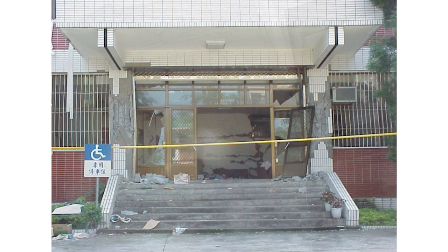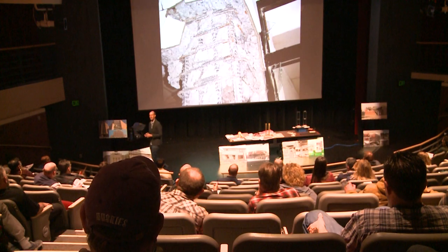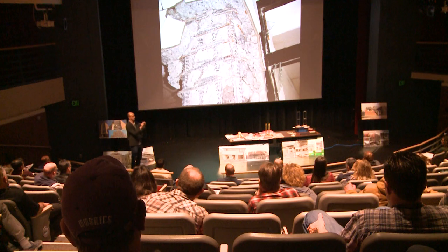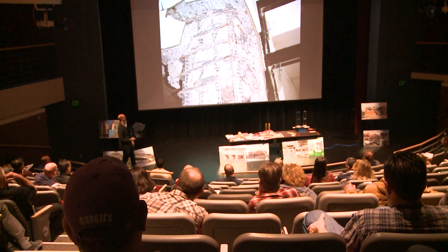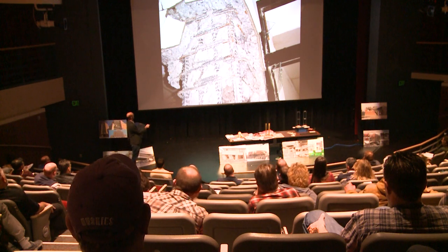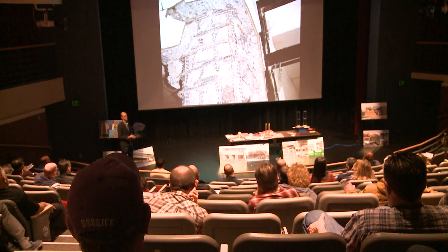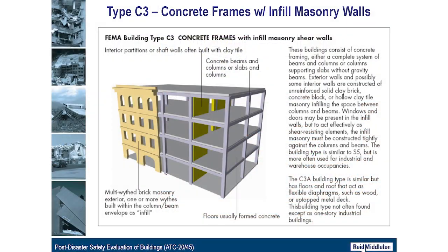I'm just going to go quickly here. Another thing to pay attention to is there's very specific requirements in this confinement reinforcement that we talked about with this model on the size of the bar and how sharply the bar can be bent and remain ductile, just like your paper clip. If you turn it a little too tight, you can snap it. Of course, it takes several cycles. And here's some examples of that where there's total fracture of these confinement bars, which may not be an intuitive failure mechanism. So something to be on the lookout for.